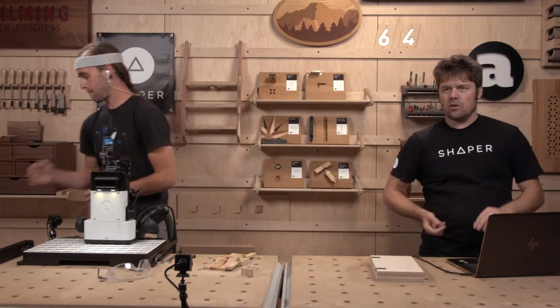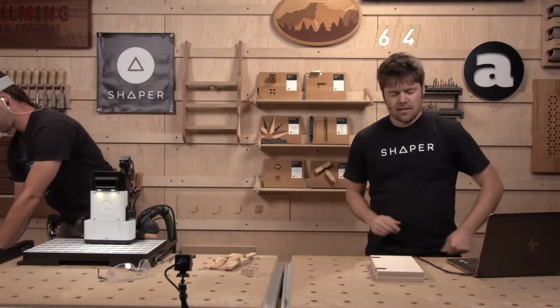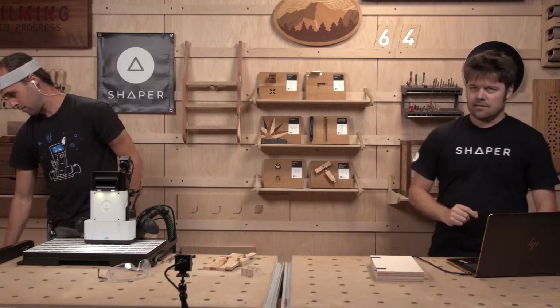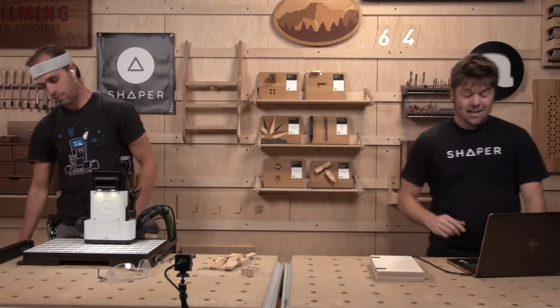If you wanted to stop, say, an apprentice or someone else in your shop from choosing the wrong anchor point, just make a custom anchor point in your file, place it how you want it, and then there's no real chance. Just use the custom anchor point, and that's the default one, so that's how it's going to come in by default. So it's just reducing risk, and it's taking care of the details in easy digital land where you can hit Control-Z, versus complicated sawdust land where we haven't invented any Control-Z yet, unless you count pocketing out a rectangle and then a positive rectangle plug, in which case maybe we have invented woodworking undo.